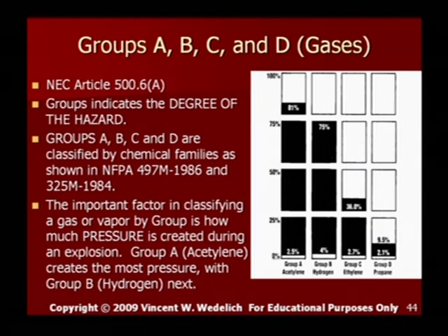So you could theoretically, and people do this, add mechanical ventilation of fresh, clean air from a safe area, and they dilute the area where it has the hydrogen so that it's below 4% hydrogen. In fact, they do it to 25% of that value, which is 1% hydrogen. So if you diluted an area that normally would have some amount of hydrogen between 4% and 75% and reduced it to 1% hydrogen, then you could say, oh, well, then that area is no longer a Div 1 location, it is now a Div 2 location.